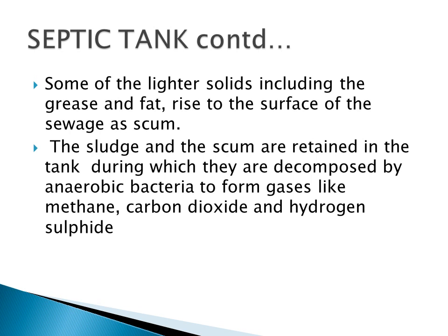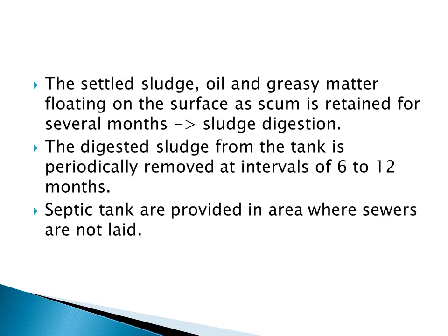And some of the lighter solids, that is grease or fat, etc., rise to the top of the septic tank as scum. So this sludge and this scum are retained within the tank, and they are decomposed by the anaerobic bacteria, and the end products will be gases like methane, carbon dioxide and hydrogen sulfide. The settled sludge will be at the bottom, whereas oil and grease will be floating on the top surface, and that will be retained there for several months for the sludge digestion. And the digested sludge can be removed after 6 to 12 months period.